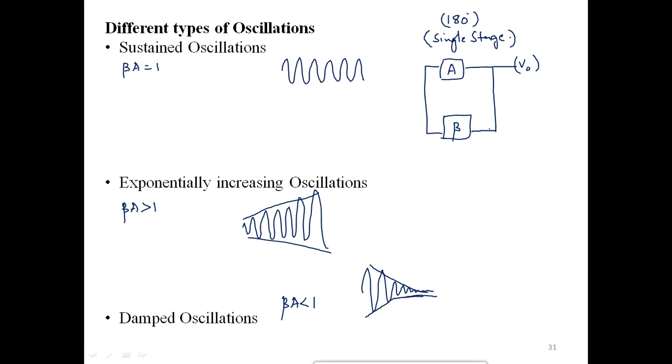Now as per the concept of the oscillator and the Barkhausen criteria, the phase shift should be either 0 degrees or 360 degrees or an integral multiple of 360 degrees. So in order to obtain 360 degrees, what should be the condition? The amplifier provides a phase shift of 180 degrees, then the feedback network must provide a phase shift of another 180 degrees.